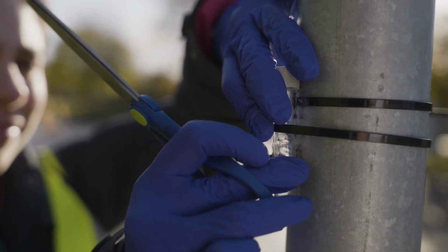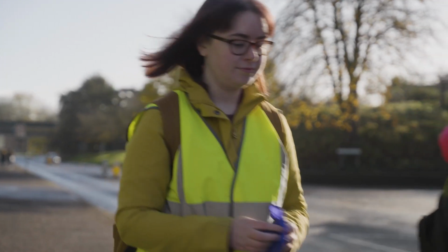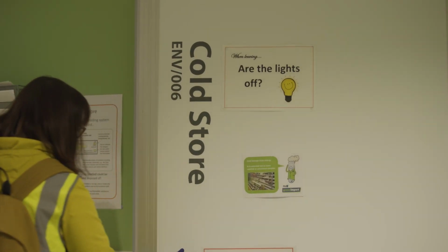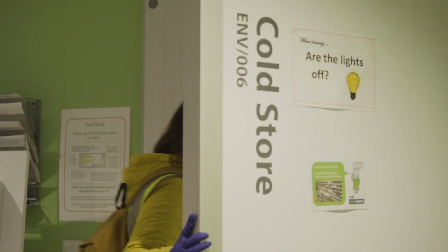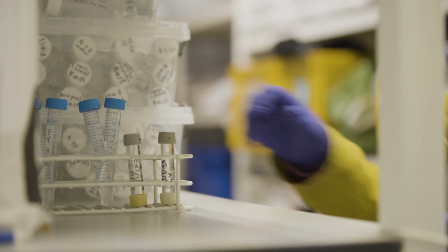Once you've collected your sampling tubes, caps should be replaced and tubes stored in sealed containers. Remember to record the time and date of placement and collection, and store the tubes in a cool place until analysis, which should take place as soon as possible and no later than 4 months after the sampling campaign.